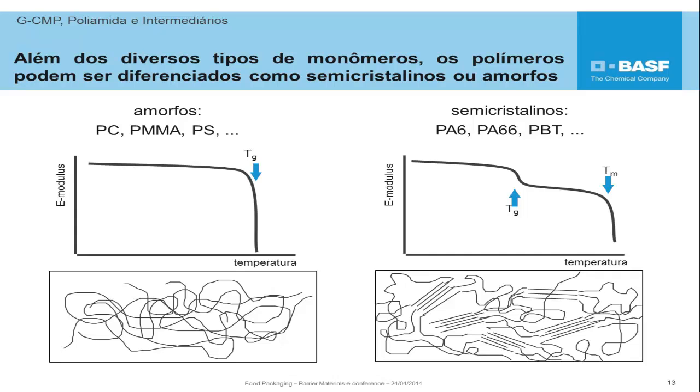But today we are going to mainly talk about amorphous and semi-crystalline. So what is the difference between these two types of materials? Amorphous materials have a structure without form and disorganized, without a clear melting temperature, defined by a lack of crystal structure; when the temperature increases, they reach the molten or liquid state. In semi-crystalline materials, part of the structure is organized and part disorganized, so by increasing the temperature it clearly shows the vitreous Tg transition temperature, which corresponds to the non-crystalline part of the material, and then it reaches the melting temperature of the crystalline part. The material is now fully melted, with the ability to closely match the shape of the transformation: a bar, a form, etc.